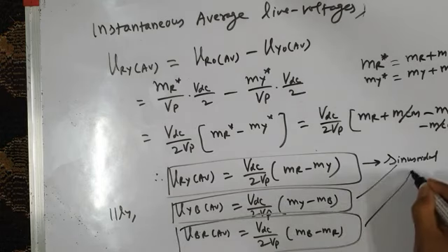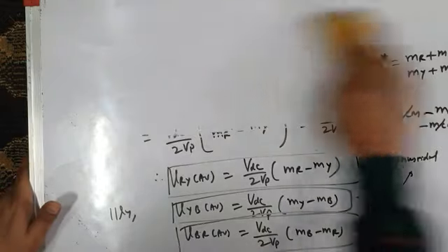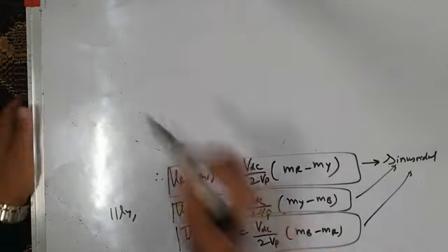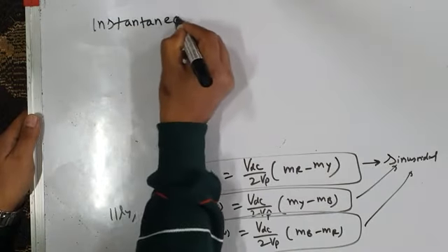So they are sinusoidal. So that means when common mode injection is done, your target reference waves or modulating waves get distorted, they become non-sinusoidal, which makes pole voltage also distorted, but line voltages still remain sinusoidal. Because these common mode signals do not appear in the line voltages, they cancel to zero. Okay, so our line voltages still remain sinusoidal. Since our line voltages are sinusoidal, what about phase voltages? Let us take instantaneous average phase voltages.